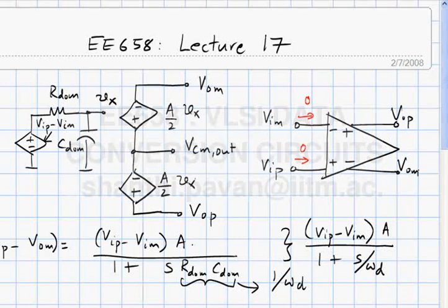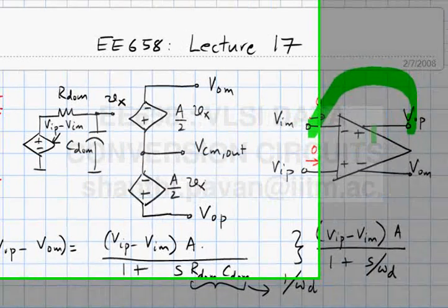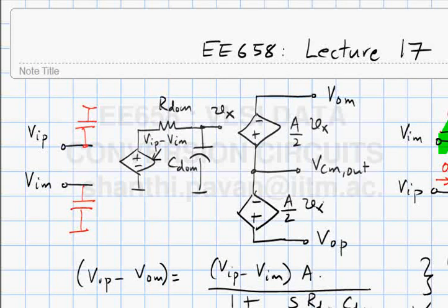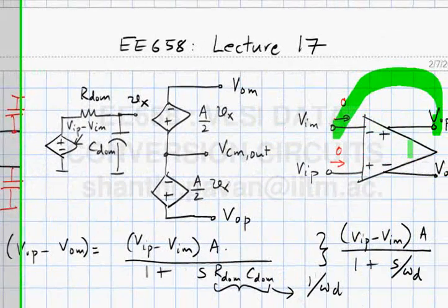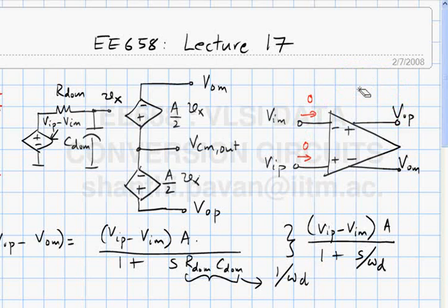We know that anyway we are going to use this in a negative feedback configuration. So, whatever we do, we will connect this back through some feedback network to the negative terminal, right? If we had drawn this with minus minus and plus minus, then all these wires would keep crossing and confuse the hell out of us, right? So, it makes sense to draw it this way.